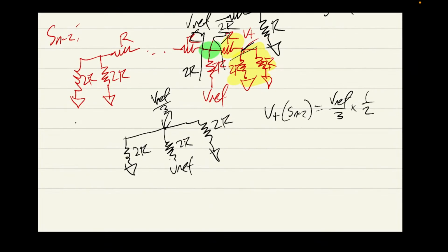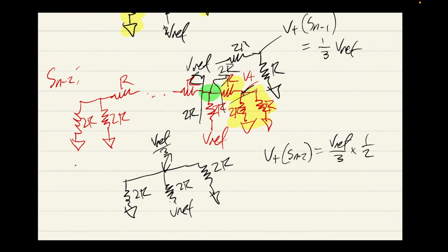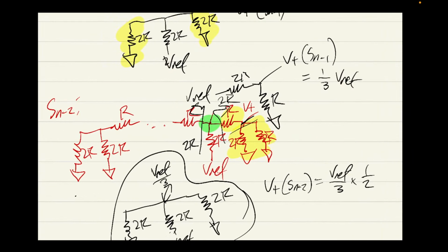And we contribute this all together with this little pattern of, okay, we always get this funky voltage division to get a third of Vref, and then a consequent number of voltage halvings on the right-hand side of it.